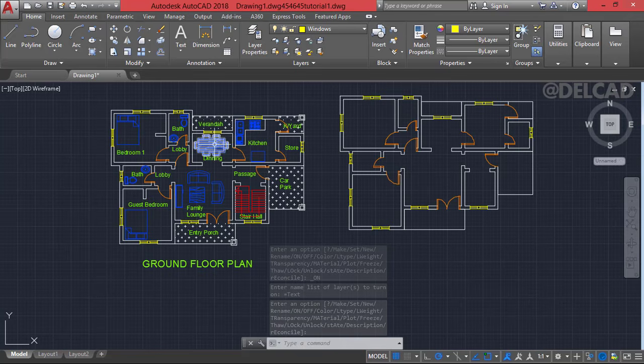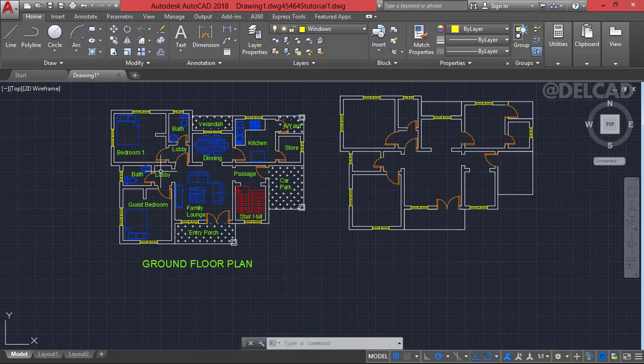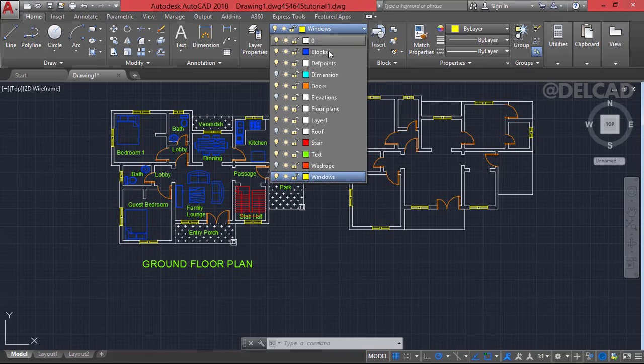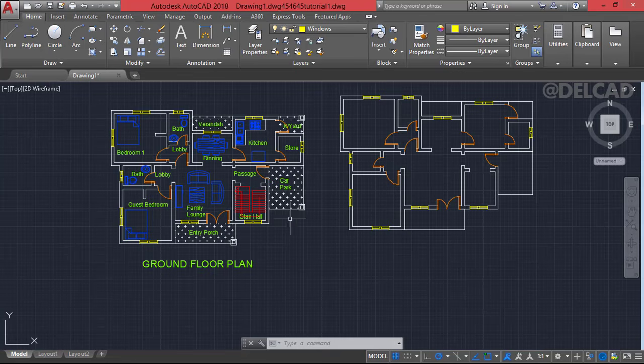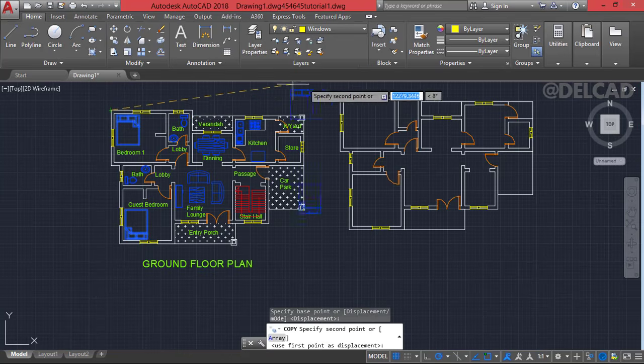So the building in this plan, we have the object in blue as the block. We have a different layer for this, having blue color. So I'm going to copy this. I've already illustrated how you can pick these blocks from the design center. So I'll select all these, right click and select similar. It's going to pick all the similar blocks contained in this, and I'll now select copy, and then select the edge of this building as a reference point and place it here.